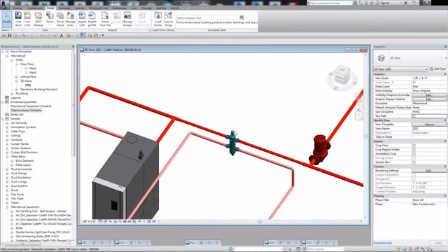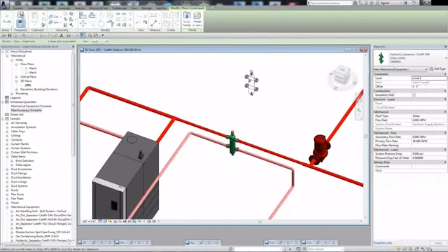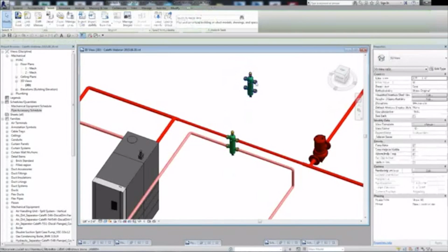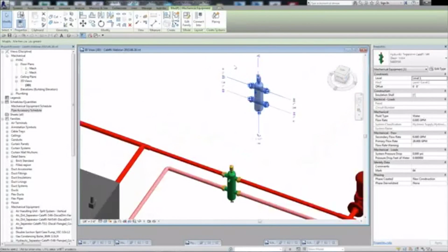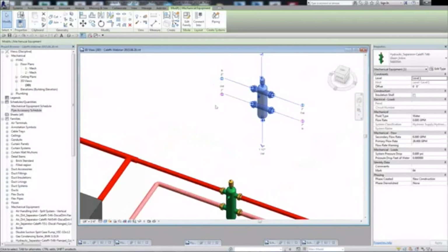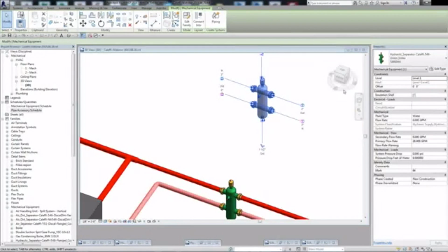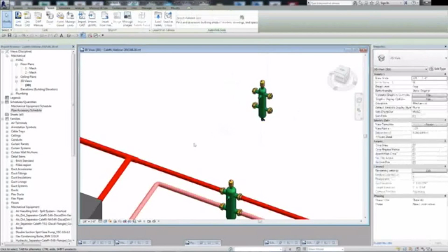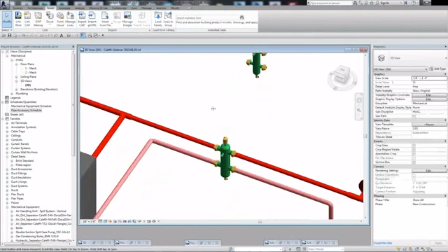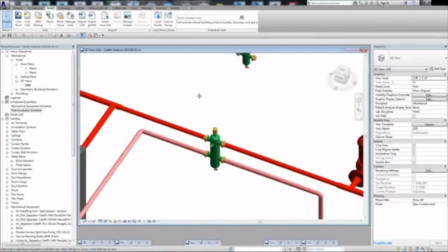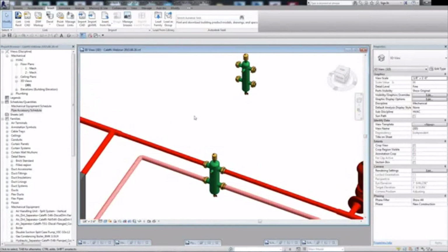No, not necessarily. But if we were to take any component and place it, and then choose a larger component, the sizing for the piping you can see here is listed as 2 inches. This is a unit inline, so if I select a smaller unit, in this case, the piping size is going to pop down to 1.25 inches. But it doesn't take all the thinking out of the project. The engineer still has to do an analysis.